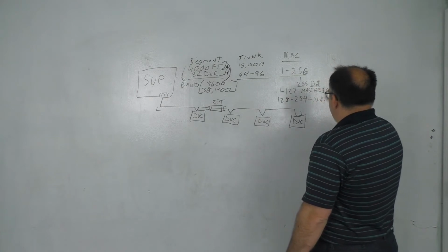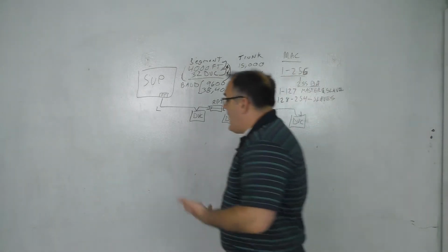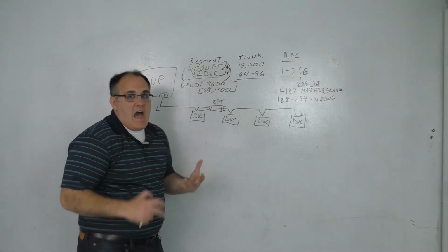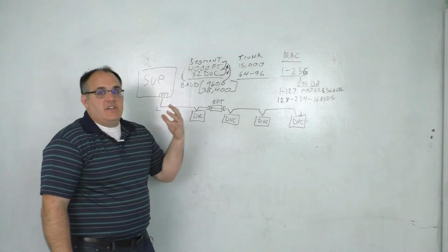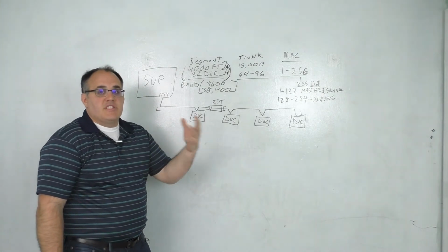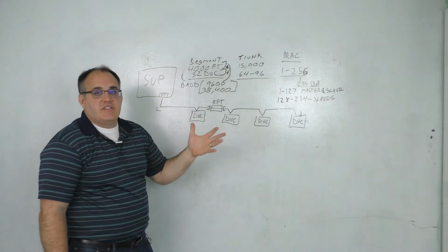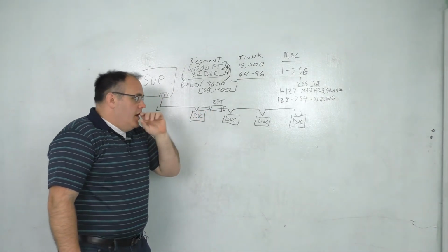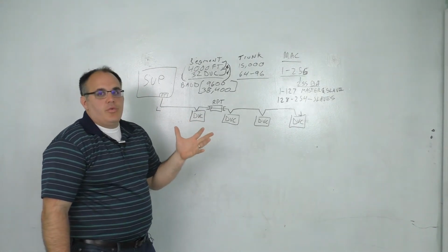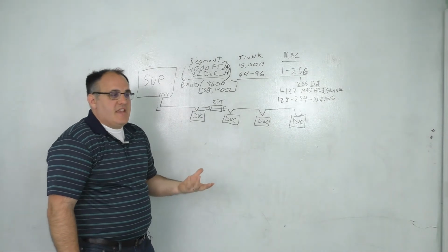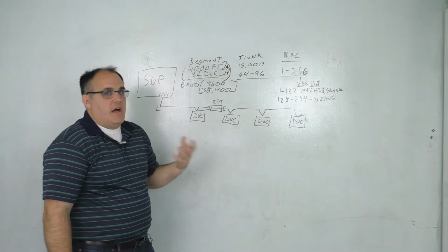Now, as you recall from episode 5, we talked about how you use services in BACnet, where there is an initiation and then a response. One device will initiate a service request, and then a device will potentially, if it is a confirmed service, acknowledge that service.